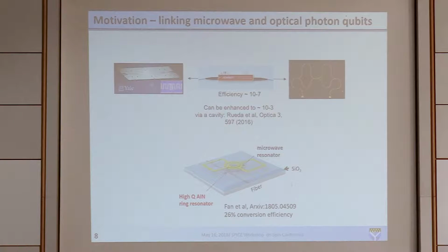And I will tell you where we are and how far away from here, this electro-optic device. So that basically tells you that an electro-optic modulator is the same as a magnon optic modulator. The difference is that you work with the electric domain or magnetic domain, okay? The magnetic domain has the benefit that you can tune the resonator. You can just change the bias field, and your resonant frequency can change to an arbitrary frequency.